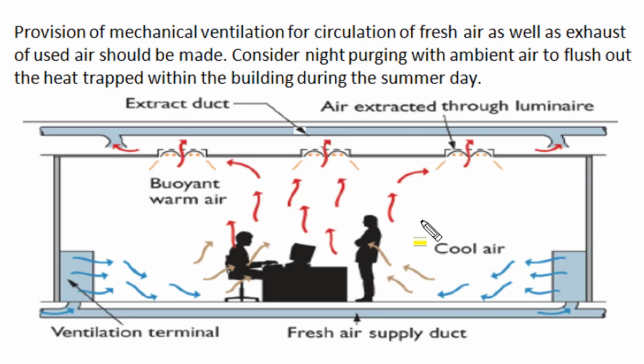For greater comfort of inmates, mechanical ventilation for circulation of fresh cool air as well as for exhaust of hot stale air should be made by mechanical means, and from fresh air conditioned supply duct, suction of cool fresh air should take place, and when it become hot, outdated and stale, and by stack effect rise, then from warm air through suitable openings in false ceiling.